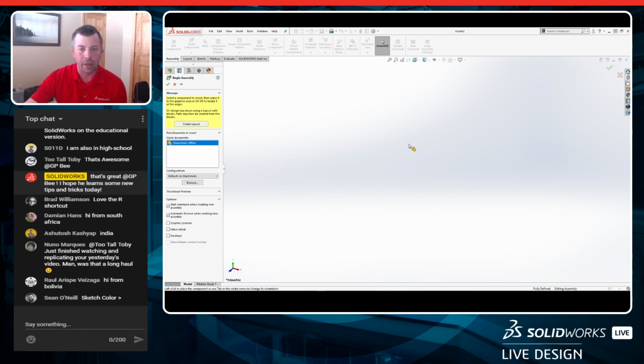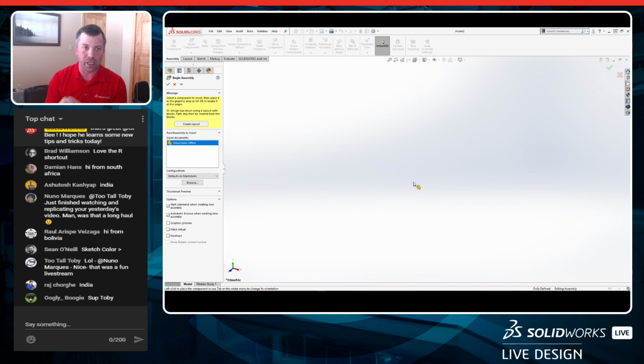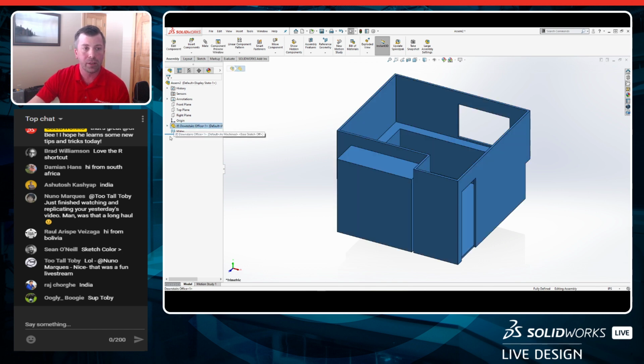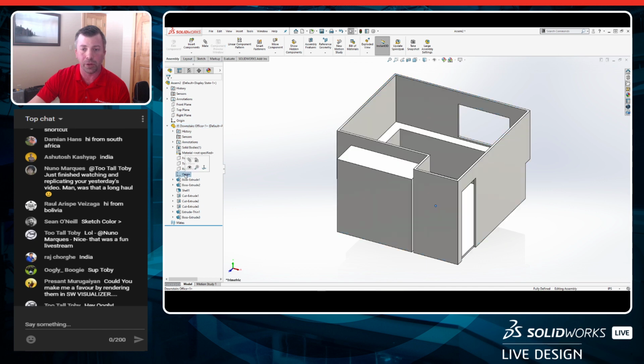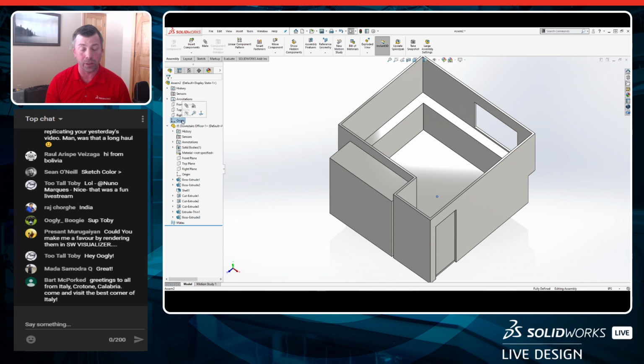If you didn't know, if you click in space when I'm creating a new assembly, this actually places that part where you're clicking. In this case, since we're using everything referenced to a shared coordinate system, so we want the top, front, and right plane to be all referenced in the same spot, I'm just going to click the check mark. All right. What this does, it actually locates that office into the same exact location. So if we look at the origin there, that little blue dot, we've got the origin here. They're right on the same spot, 0, 0, 0. And we'll use this same origin for anything that I do in this design.